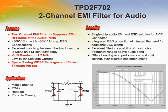The TPD2F702 exceeds plus or minus 30 kV ratings per IEC 61000-4-2 contact and air gap specifications. It is primarily used in the mobile phone audio headphone speaker interface, but can be used in other audio applications.